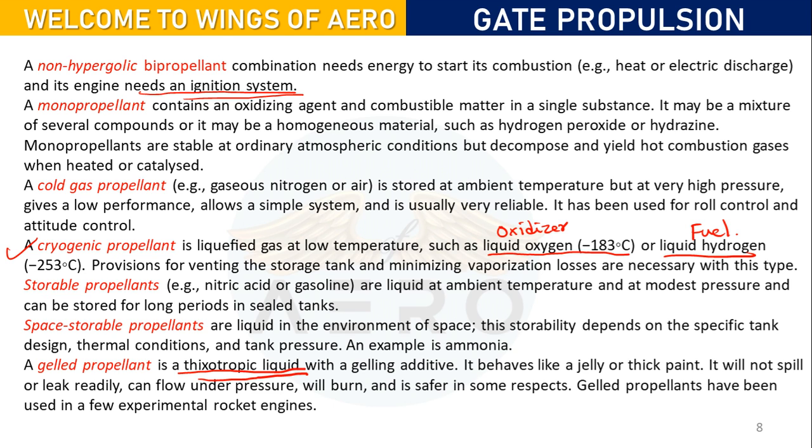So the first characteristic was that it doesn't require any separate plugging of injectors. Controlling will be much easier in the gel propellant, especially as compared with all others. But we cannot use it for big engines, and it doesn't produce a huge specific impulse actually.